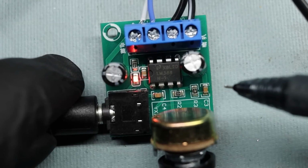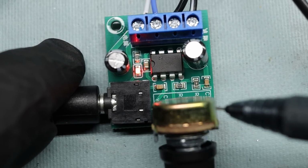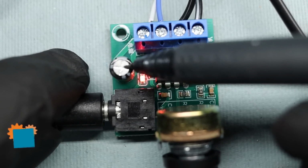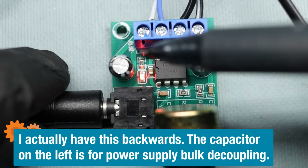So here's a little bit of a close-up of the LM386 amplifier board. We have a potentiometer here that's part of the gain control circuitry. This obviously sets the gain. This is the output for the speaker terminals, and this is the DC voltage supply. So we have a capacitor here that is part of the output network for the speaker. So that blocks the DC from getting to our speaker.